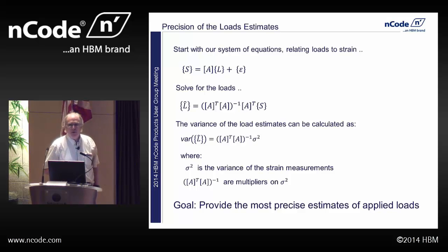There are calibration issues and placement issues, so there are always errors involved with these strain measurements. If I account for those errors, take the original equation I had for the least squares fit, strains in through this least squares approximation to give me my estimated loads, and put in the quantities with the errors and do a fair amount of math,